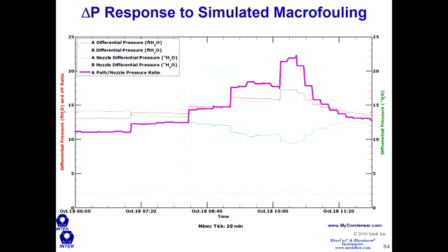And so with both of those DPs per path, those are shown here. We've got a differential pressure on the A path and a differential nozzle pressure on the A path, similarly with the B path here. And so if you plot the ratio of these two measured values, you can calibrate this output to the number of tubes that are obstructed.